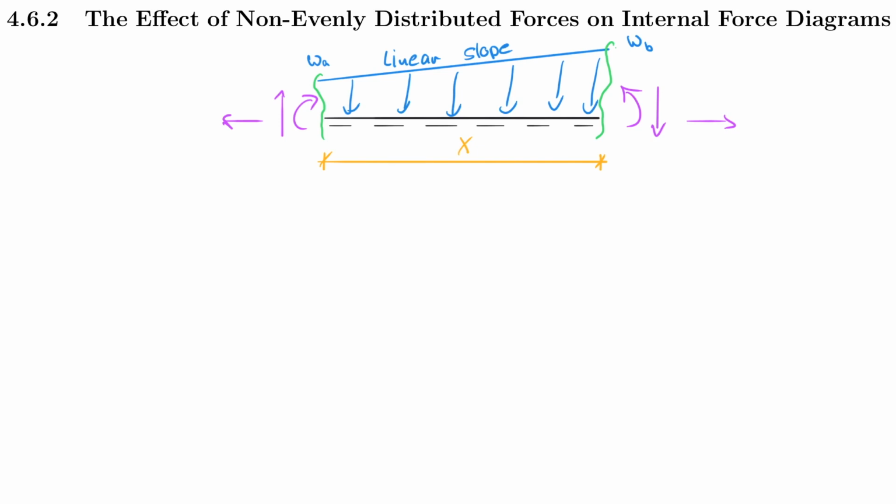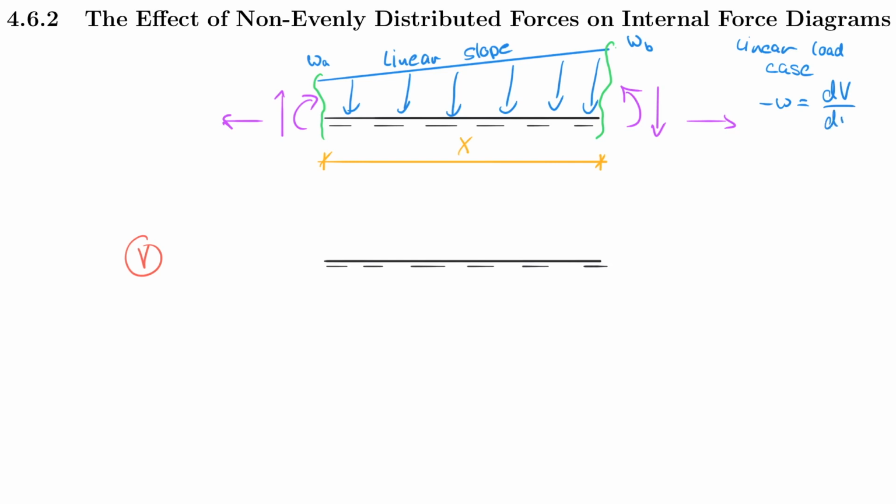But my goal now is to think about what happens if I want to apply that load case to my shear force diagram. And to draw the shear force diagram, I start with my rigid body. And I start calling this the shear force. And the thing that I remember, right, is that here I now have a linear load case. And I also remember that minus W is equal to dV/dx.